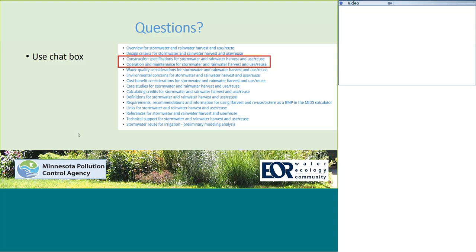Whereas if you're taking it off of a site that has a lot of sediment moving around, a lot of activity going on, runoff from parking lots, et cetera, that get sanded, then now you need to configure your system a fair amount differently just to be able to deal with the physical setting of those. So you need to think through how much you want to invest in the treatment and operation and maintenance. You may have originally thought you were going to do stormwater from all surfaces, but as you go through your design process, you may want to back up and say, if I have a very large roof, maybe I'll concentrate on treating that as one of my primaries where I'm doing my volume control, just because there are so many fewer issues that go with that.